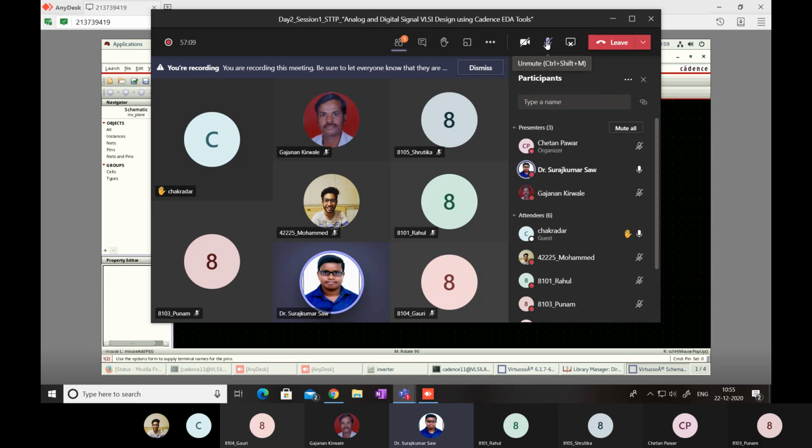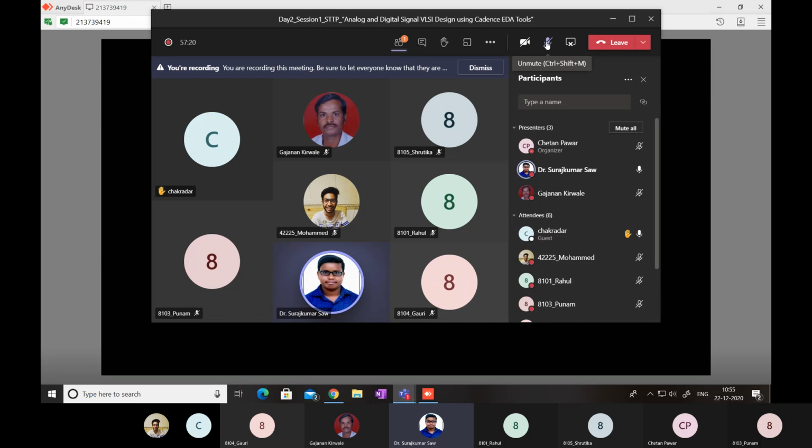Yeah, Shrutika, change the voltage level. You have to keep two voltages at different values. One at 1, next is 0. Similarly, yeah, very good. Go for period. First voltage you have given 1, next you have to put 0 because it is a pulse form, right? And period 100 nanosecond, whatever you want. In the first input, if you are providing the period as 100 nanosecond, in the second input you just change it to 150 nanosecond. Accordingly, you change the pulse width also. Put the delay time, whatever you want to do. Yeah, 10 nanosecond, 5 nanosecond, whatever you want.